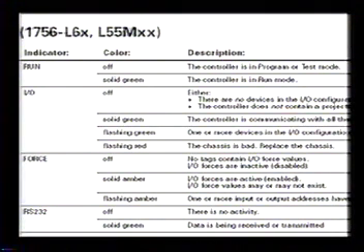Now, when you're downloading that firmware, don't touch anything. Make sure you've got a solid power source. You do not interrupt this, because if you're downloading your firmware initially, it's called controlled flash, and we covered that in part 2, I believe. If you interrupt that, it will disable that I/O, and then you have to ship the processor back to Allen Bradley, and they have a whole service for this, and then they ship it back to you. So you don't want to do that. I see a lot of people, they say, oh, it says don't hit this button, and they do it. I don't know why they do that, but don't do those things.